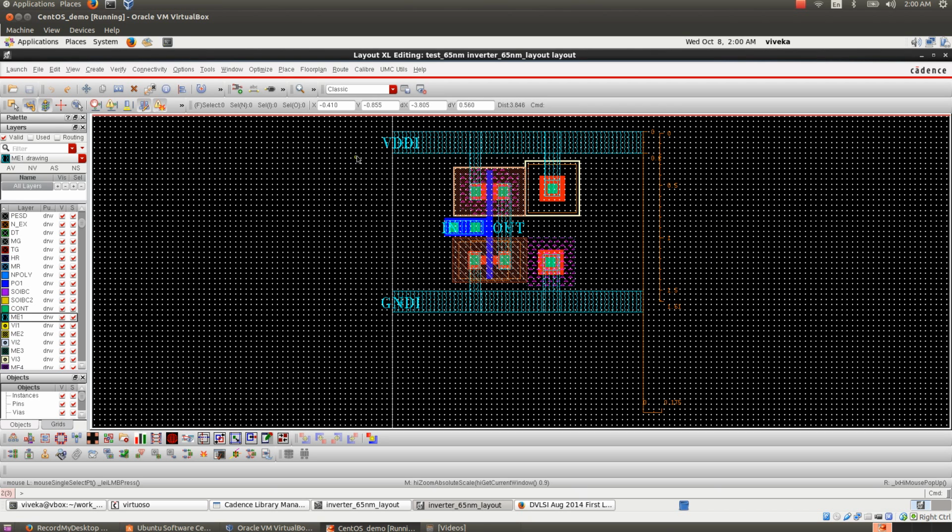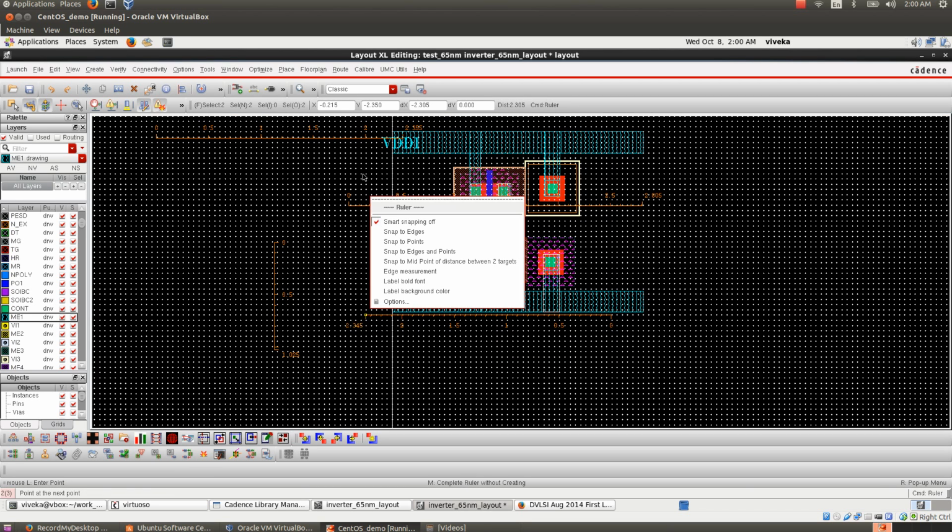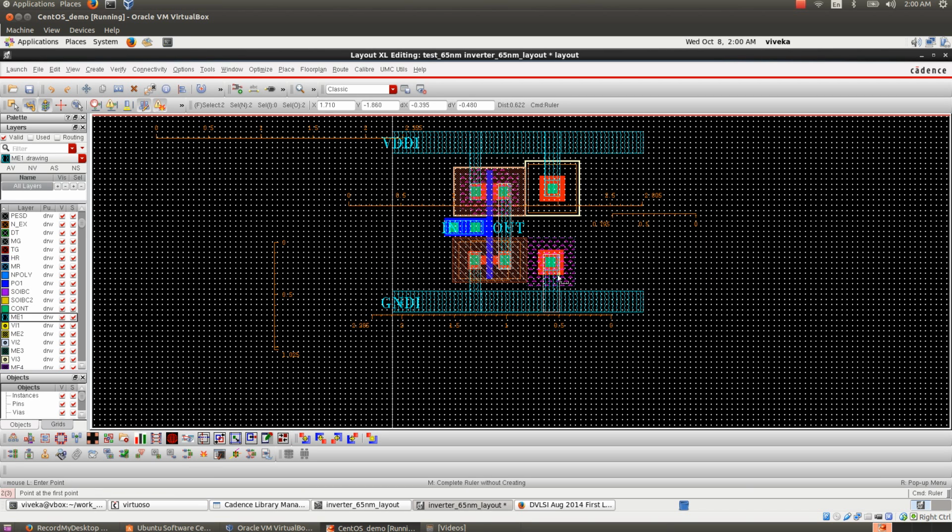and hit F. The rulers that we created can be removed by hitting Shift K. That's something I did not tell you earlier. If you hit K, it brings up the ruler and you can measure stuff. You can have lots of measurements, and that can get really ugly really quickly. So to remove all of them, you can hit Shift K and all of them disappear.